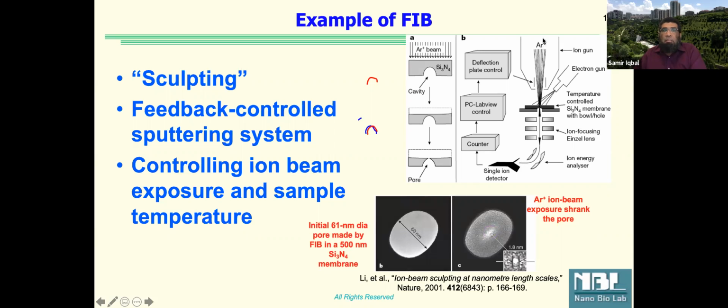So this is an example of an ion beam machine where they are throwing ions. The ions are coming out of ion gun, and we are making them with these 2 plates you see. These are used to deflect them. So again, electrostatically, you can move them and make a very narrow beam coming out of that machine, and then you can use to write on the surface.